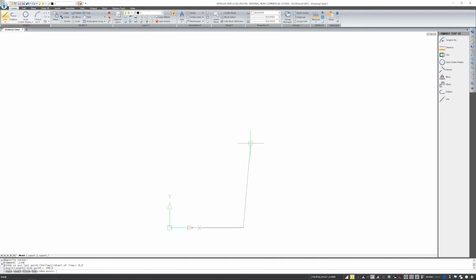Now, when I would like to go up in absolute, let's say by drawing a rectangle, then I would give the y value, which I previously set at 200. The number of units up, let's say 500, and confirm it with enter. And I can draw a whole rectangle this way. So now there will be 0 in x, and there will be 500 in y.